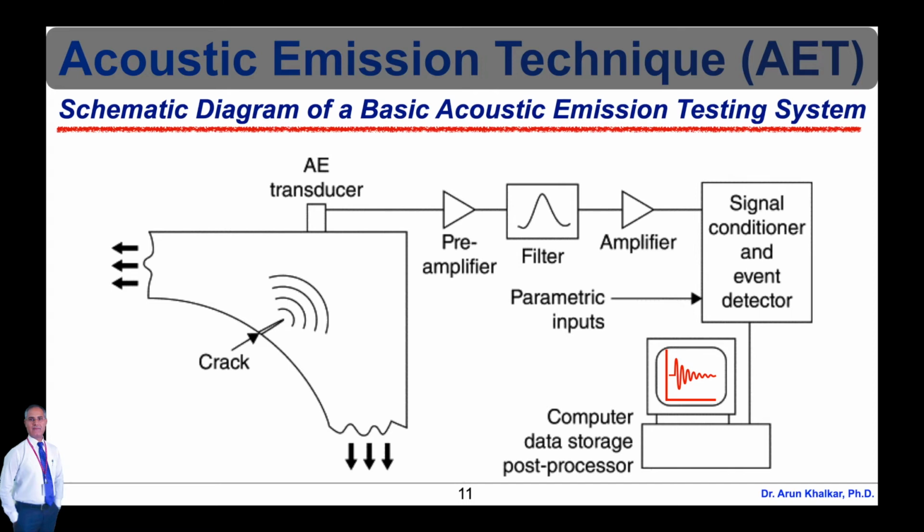After passing the AE system mainframe, the signal comes to a detection or measurement circuit as shown in the figure. Note that multiple measurement circuits can be used in multiple sensor or channel systems for source location purposes. At the measurement circuitry, the shape of the conditioned signal is compared with the threshold voltage value that has been programmed by the operator. Signals are either continuous, that is, analogous to Gaussian random noise with amplitudes varying according to the magnitude of the AE events, or burst type.